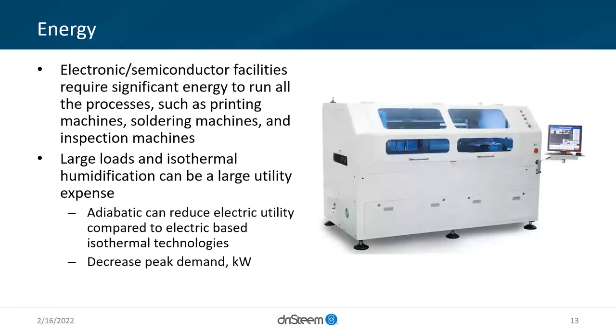And I want to do some trimming with an electric unit because the turn down is that much greater. So there are solutions like that to mix and match depending on the goal, where we get a bulk done with adiabatic because it's energy saving essentially, and where we want that fine tuning at that very specific spot with, let's say, an RTS, for example, a resistive to steam unit.